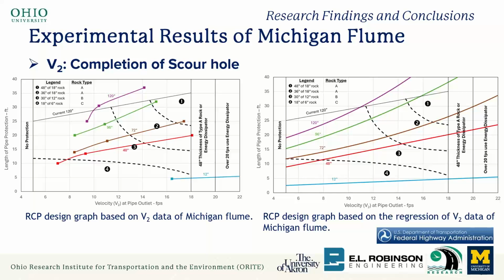Do you only recommend figure 1002-4 for relatively low slope outlet culverts not outletting to a bend, and then above that going to something like HEC 23 DG4? Danny, I'll give you that. I don't know which number means which offhand. I'm sorry.